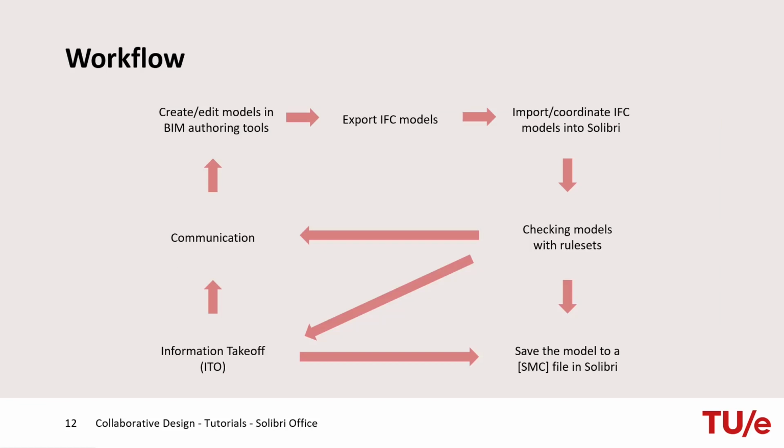This is a general process of using Solibri. At first, building models are created, by you or other people in BIM authoring tools. Then, they are exported through IFC format and then imported into Solibri. Now you can use rule sets in Solibri to check the models. After the checking process, you can do an ITO or communicate about issues with other people. This information can subsequently be used to edit and improve the model.